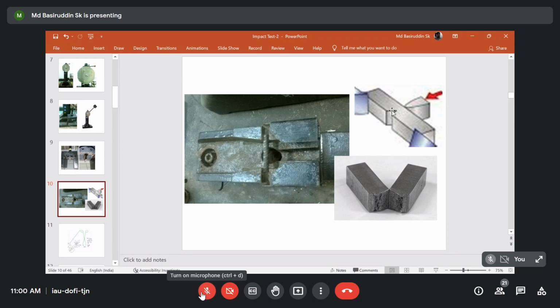I think Professor PCC has taught you the different modes of fracture, like mode 1, mode 2, and mode 3. Just to recapitulate, you can think of the mode 1 fracture as the crocodile mouth opening mode of fracture. Once the mouth opens, it ends up with the complete separation of the two halves, or the complete fracture of the specimen. These things will not happen if the material shifts along the horizontal direction.